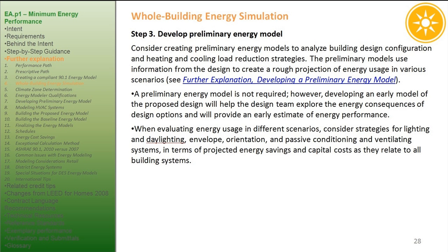Step 3. Develop Preliminary Energy Model. Consider creating preliminary energy models to analyze building design configuration and heating and cooling load reduction strategies. The preliminary models use information from the design to create a rough projection of energy usage in various scenarios. See further explanation, Developing a Preliminary Energy Model.